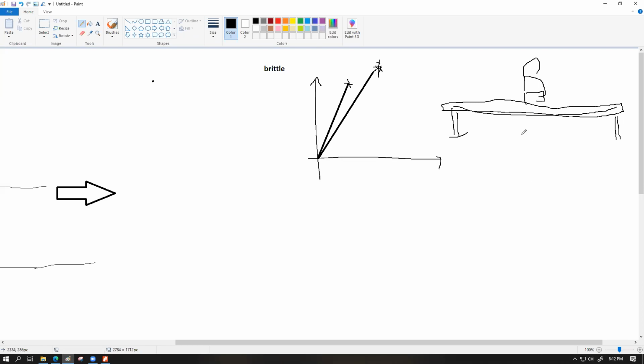If you take out all of those shattered pieces and try to measure the curve, to see whether any of the pieces retain this curve behavior, you'll find that there is no such piece. Every piece after breaking would go back to its original flat surface. The whole specimen broke, but each individual piece came back to its original shape. You broke the specimen, but the material did not undergo any plastic deformation whatsoever. Plastic deformation means some permanent deformation is present within the object when the forces are removed.